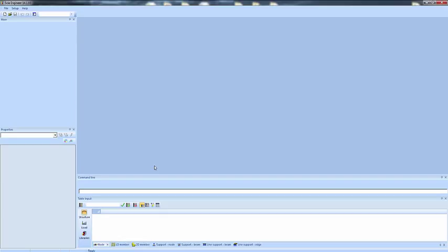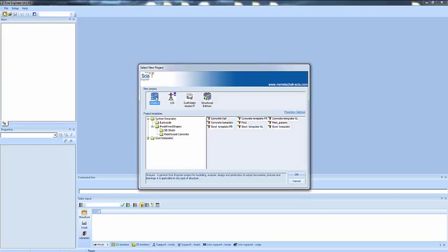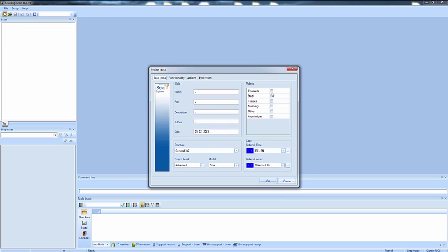So in the next step I will show you how to input a structure and how to model traffic loads onto this structure. I have opened Scia Engineer and I will start a new project, an empty project. It's also possible to use templates, which are provided here, but in my case I will start from scratch. I'm using concrete and I'm setting my default material to C40, and I'm using the general 3D environment.